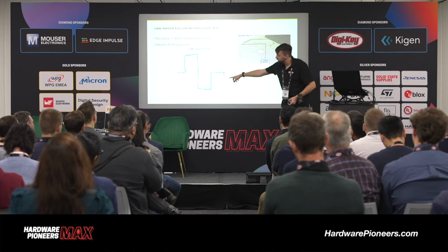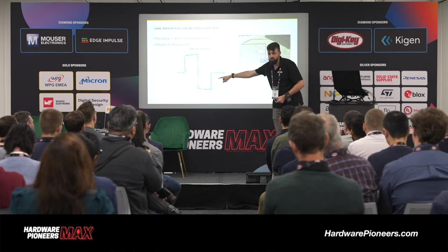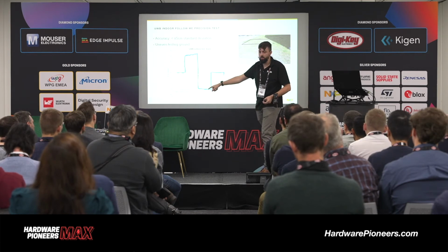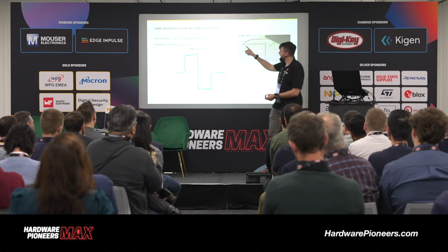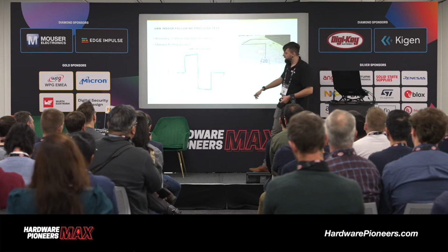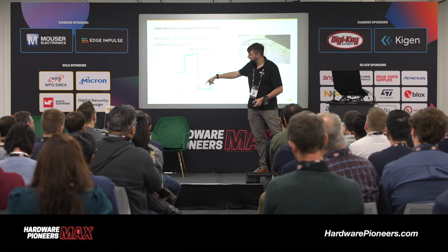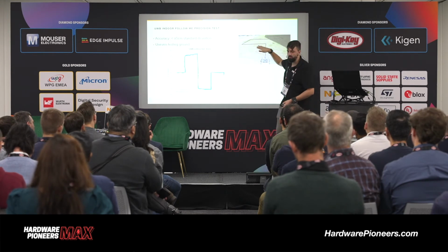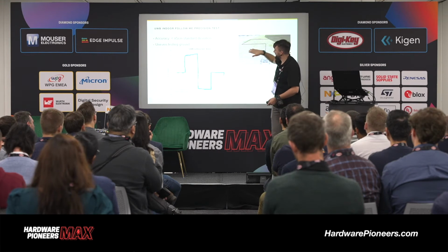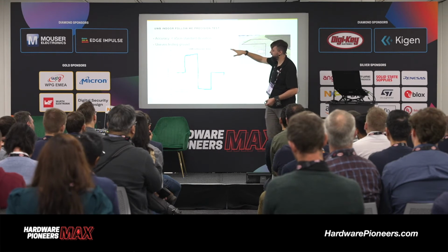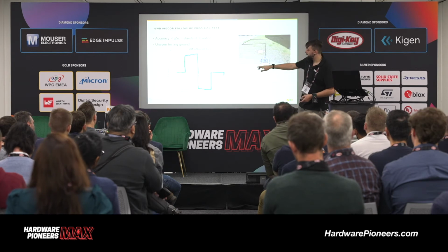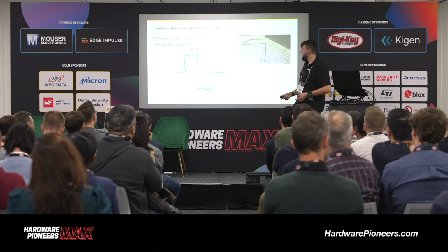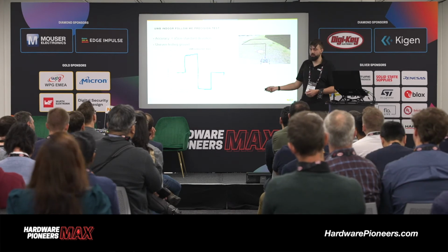And on the left here, we have the representation of the measurements. We have in blue the measurements, and in green is the path it should look like as I taped it on the ground. As you can see, it follows pretty closely along all of the lines, except for here, which is where the ground slopes downwards a little bit. So the test environment wasn't perfect, but the measurements correlate very well with the actual marked track.